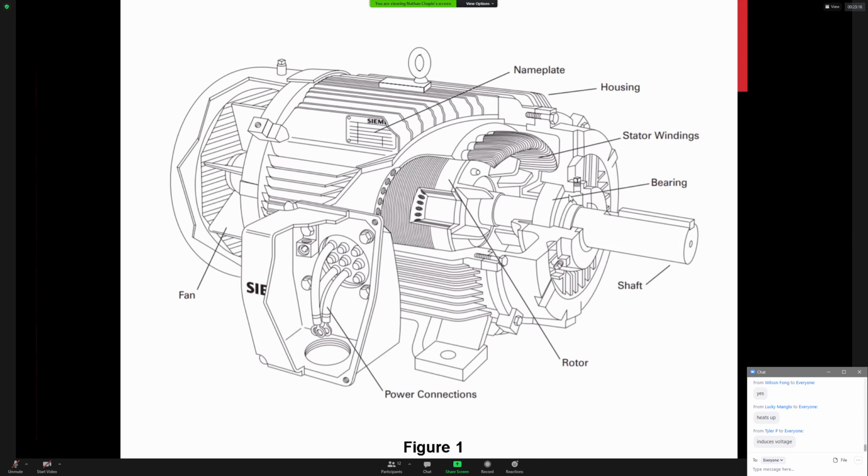When we have a variable frequency drive, the way that it works is the output induces way more eddy currents into non-current carrying metal parts, which means that the bearings actually have to be oversized and made differently, depending on application. But any motor that's rated for working with a variable frequency drive will have oversized bearings and also an insulating grease, a very specific type of grease that's in those bearings. And of course, we have our connections.